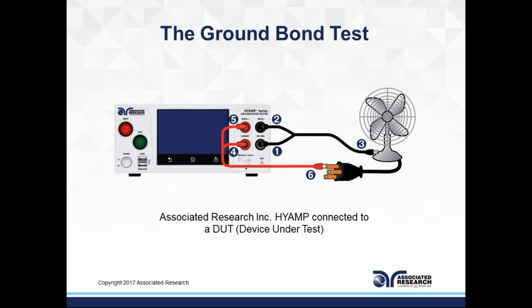With the Kelvin method, known as a 4-wire measurement, you have 4 different wires, two on each side. So you're applying with two wires and you're returning with two wires. One of the wires is thick enough to handle the current. The second wire acts as a voltage meter that allows you to bypass any of the resistance that may be added on due to the system.